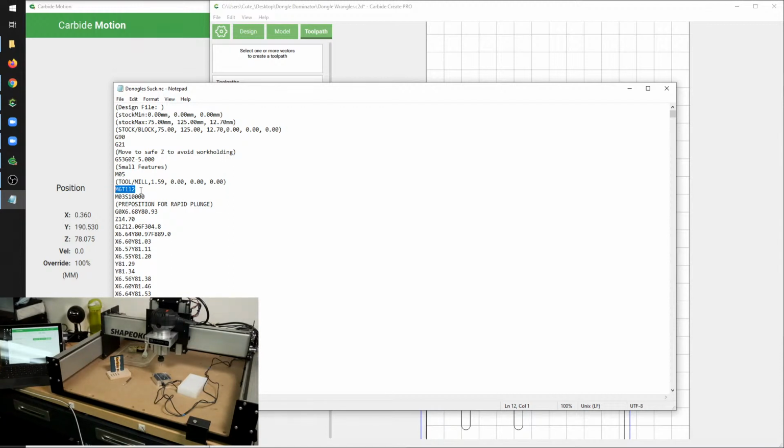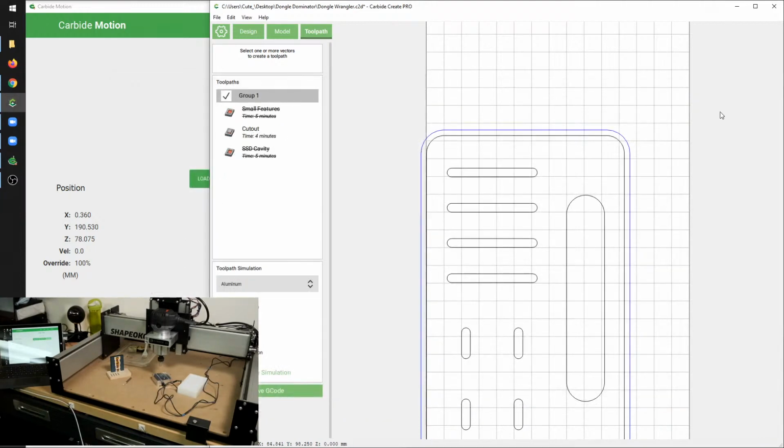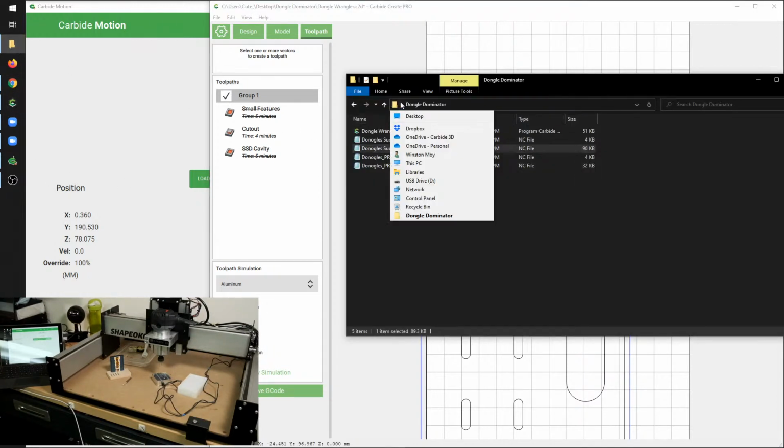All right, how do I import a picture from the internet? A lot of people have the idea that when you start machining, you can just download a JPEG, throw it into Carbide Create, and off it goes. There are no vectors or line data in JPEGs. So what you would want to do, let me see if I have anything here that's useful.